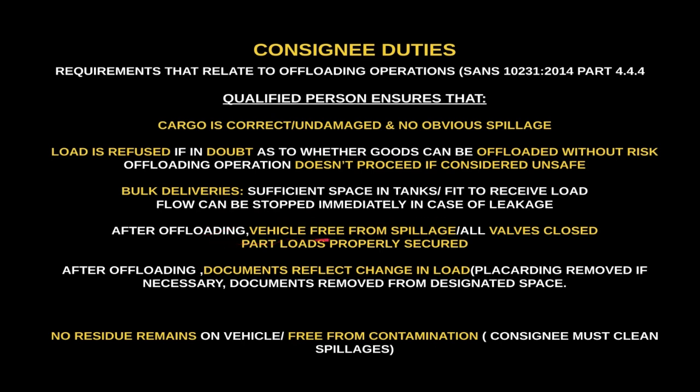After offloading, the vehicle is free from spillage and all valves are closed. Part loads are properly secured. After offloading, documents reflect the change in load. Remember, this was for part loads. Placarding is removed if necessary, and documents are removed from the designated space.